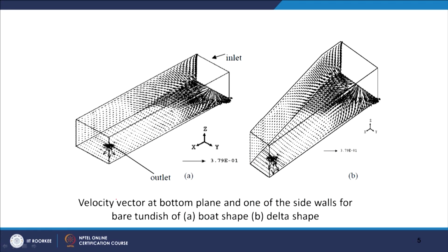So, if you look at what we did again, for getting that you need to solve these equations. You treat the flow as turbulent, so you have to solve the appropriate equations even for turbulence. If you take the K epsilon turbulence model, you have to solve these two extra equations for K and epsilon. You can take any other turbulence model, and then ultimately you try to